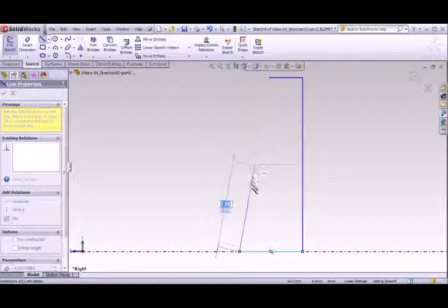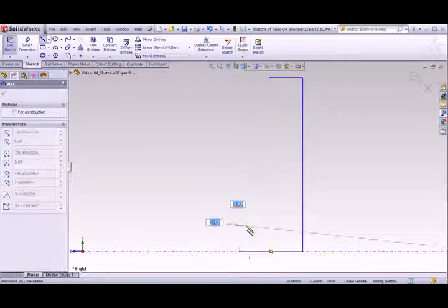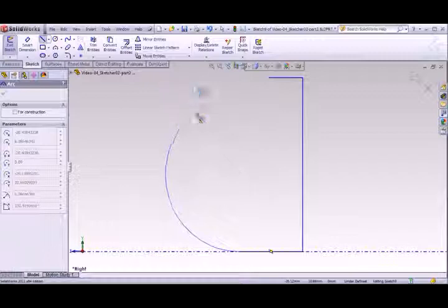All I have to do is come back down here and mouse over this same point, and it'll convert my tool to an arc tool. So if I mouse over this point, it lets me choose whether I want to do a tangent arc, or mouse over it again and come vertical. It'll let me do a perpendicular arc, which is what I want in this case.